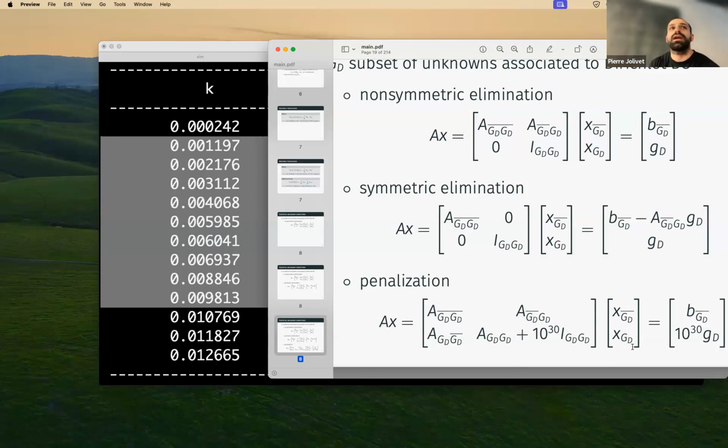Okay, so D is the Dirichlet nodes. This is exact penalization because we are using double precision arithmetic. In practice, we have a very high order of magnitude with this 10 to the power of 30 compared to the finite element analysis. But you can see that when you compute matrix-vector products or stuff like that, it can introduce artificial noise. That's why we had large values in the error just previously. And so I often advise people to use other values for TGV.